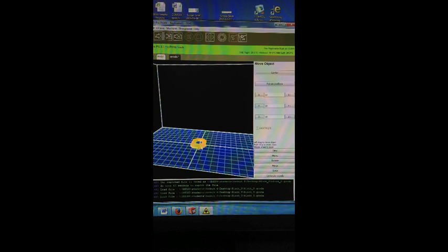Once the G-code has been generated, select the G-code tab, and this brings up the whole code. We have to manually check the plate temperature. This is about 10 lines down, starting with the command M109. Check and make sure that the S temperature corresponds to the correct material.